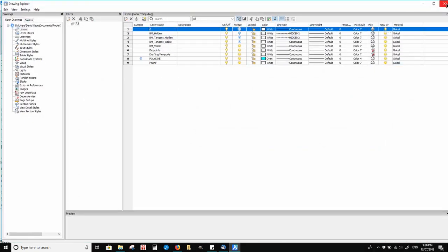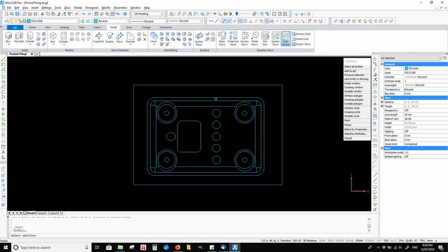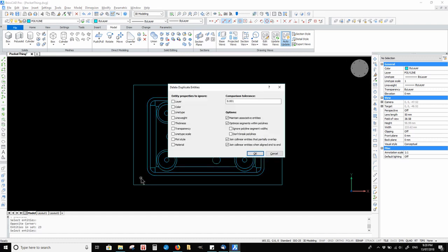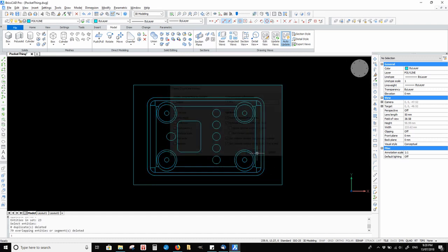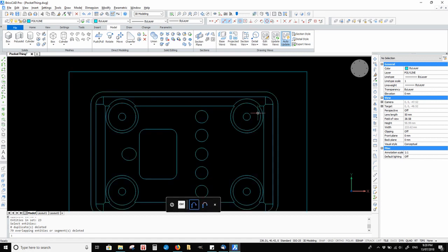In the process of making polylines with the boundary command, we have made too many overlapping lines. Remove them with the overkill command. We just have to manually trim away some unwanted lines.